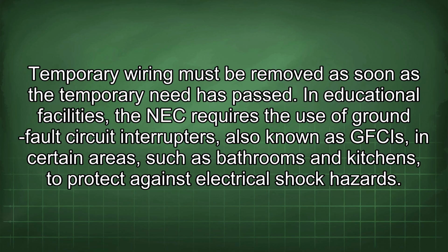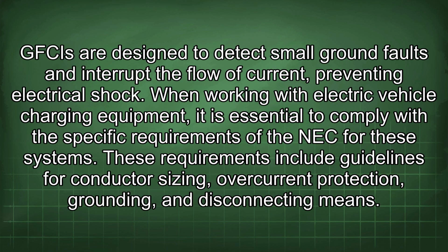In educational facilities, the NEC requires the use of ground fault circuit interrupters, also known as GFCIs, in certain areas, such as bathrooms and kitchens, to protect against electrical shock hazards. GFCIs are designed to detect small ground faults and interrupt the flow of current, preventing electrical shock.